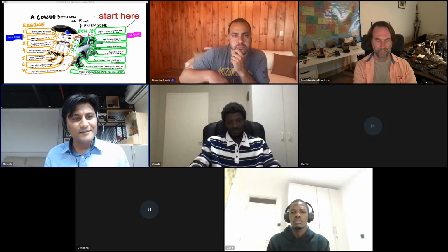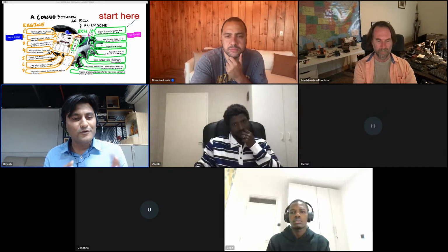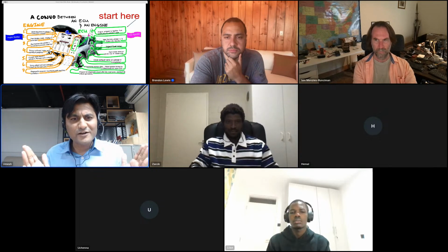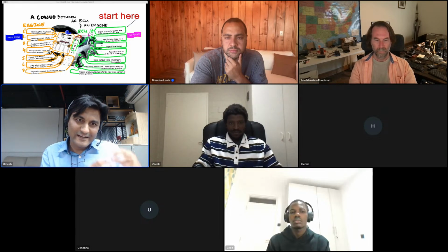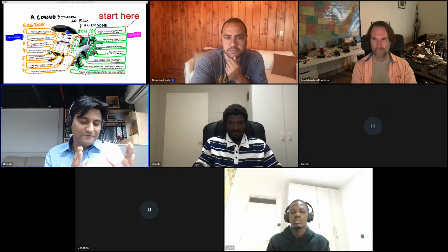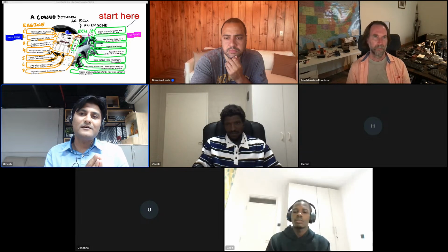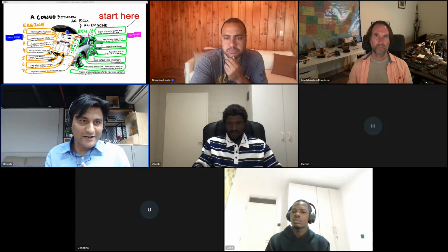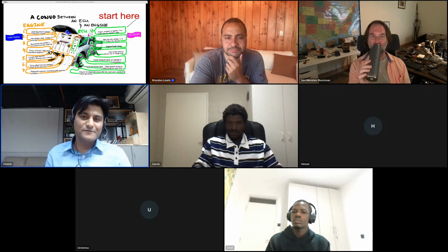That's where I then, and again, I would not quickly go into a commercial RTOS. I would look for something which is very easy, let's say FreeRTOS. It's not really an RTOS, it's just a scheduler. So if that is able to do it, then I would probably do it. And if I need more advanced stuff out of the box, then I would go for a commercial RTOS. So that's how there are steps as you start building an application.